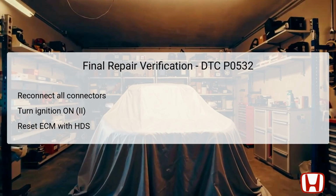Following reconnection, turn the ignition back to the on 2 position to power up the vehicle's systems. Utilize the Honda Diagnostic System, HDS, to reset the ECM, which may have stored previous error codes and settings. This reset process is crucial to allow the ECM to relearn parameters relevant to the air conditioning system and to prepare it for accurate functioning.